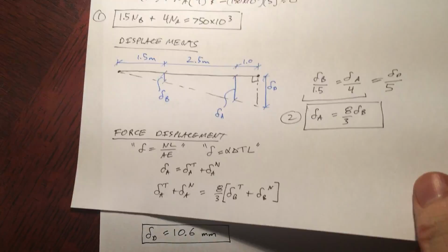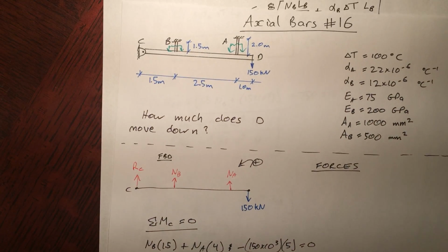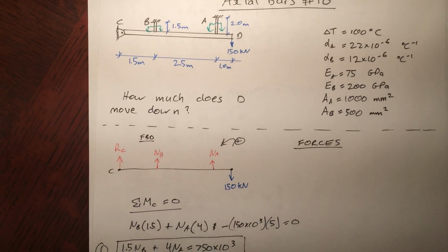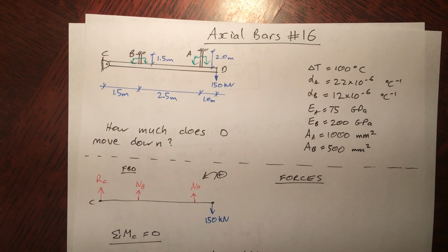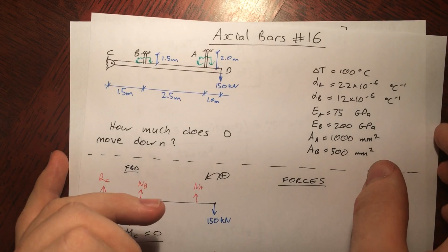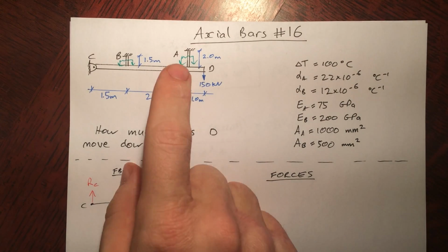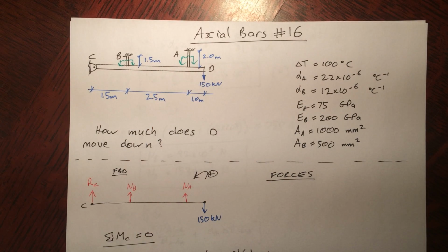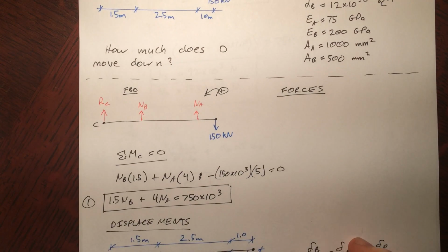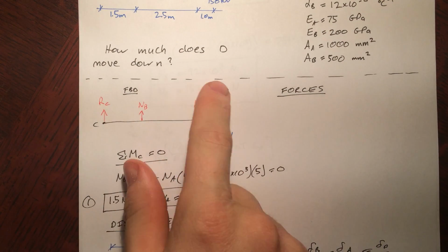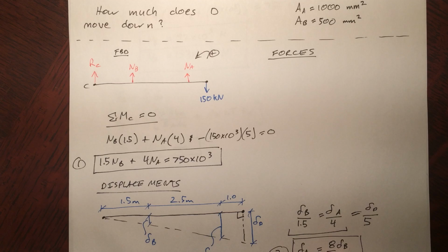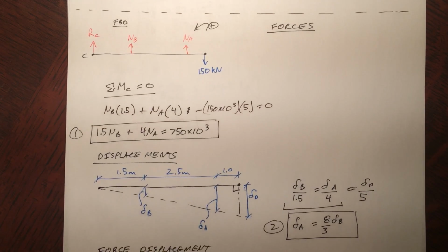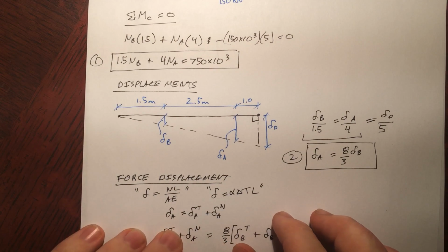So in a quick review, the process is always more important than the answer, because the answer only works for one question, the process works all the time. We made sure we had an initially clear looking drawing, made a clear free body diagram, labeled all the forces and the directions, and that allowed us to find an equation that consisted only of forces, or in this case moments, but a moment is just a force at a distance.